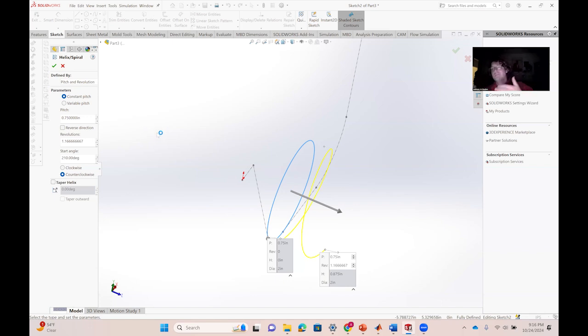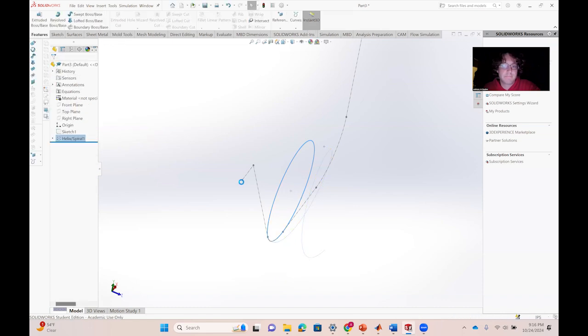However, it works the other way as well, because if you make your pitch a little bit greater, then your ball has to turn a lot more, which also induces a lot more friction. If the ball is just going in a straight line and doesn't have to turn, and therefore be forced up against the sidewall, you could have some losses there as well. So there's a bit of a balance. I found a track width of 5/8 of an inch and a pitch of 0.75 seems to work pretty well with the marbles that we have. Okay, so enough about that. Gonna hit check mark on that.